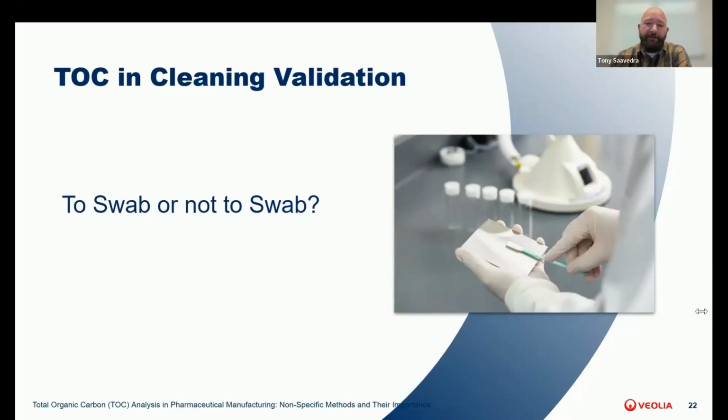When deciding between swab or rinse methods, consider the equipment design, product characteristics, right? Is it soluble or not? Your cleaning process, regulatory requirements, and resource availability, as swabbing can be more labor intensive and time consuming. Remember, whichever method you choose needs to be validated. You must demonstrate that your chosen method can reliably detect residues at the levels of concern.